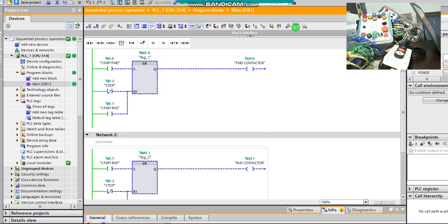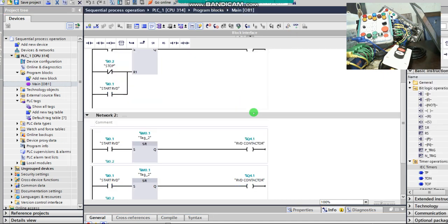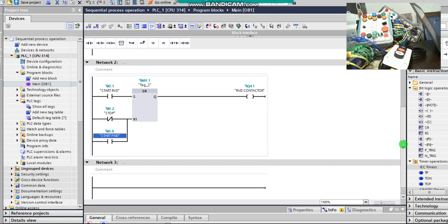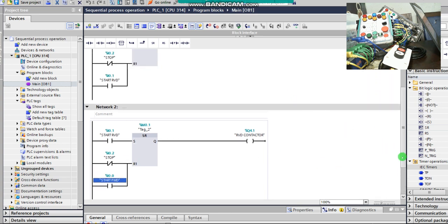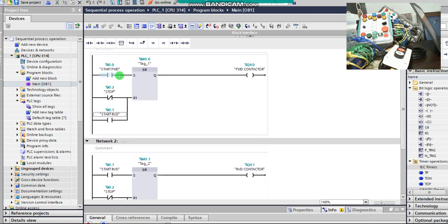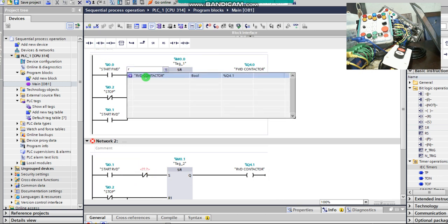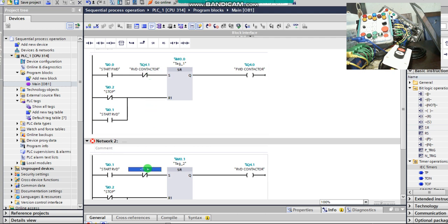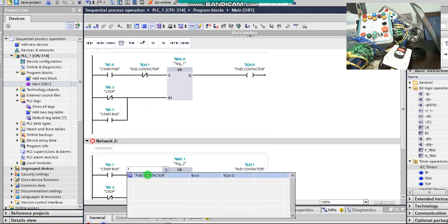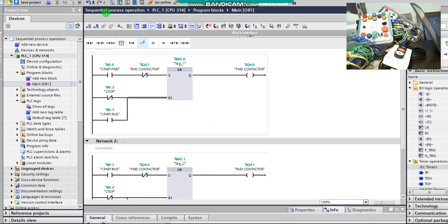All right, there's one other aspect of this particular design that I want to draw your attention to, which is the interlock system. Interlock system here, to interlock this operation. But with the forward and the reverse operation, we can override it. Like I said before, if forward operation is on, backward can also be initiated.